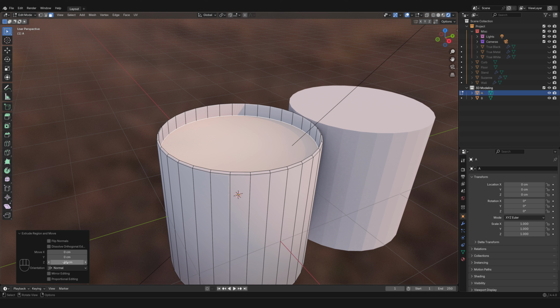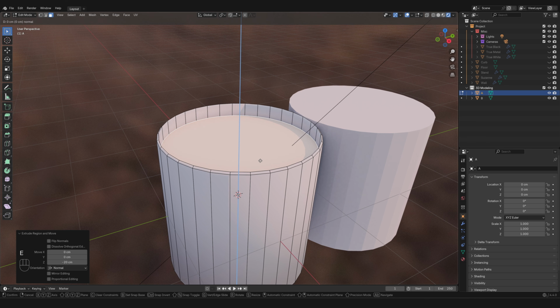Now, just like you can concatenate commands when you're moving stuff around, you can do the same with 3D modeling commands. So now I'm gonna press E, which is gonna extrude, but right away before I move the mouse or type anything else, I'm gonna press S as in scale. And so right now I am extruding, but I'm creating a section with the geometry in place.